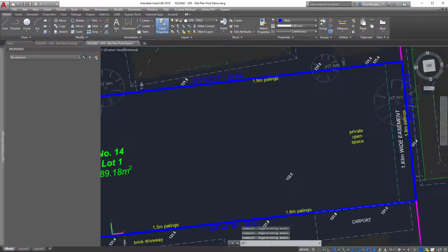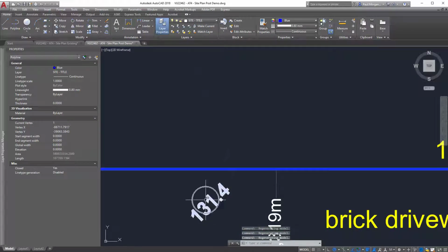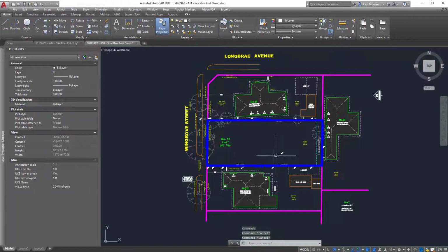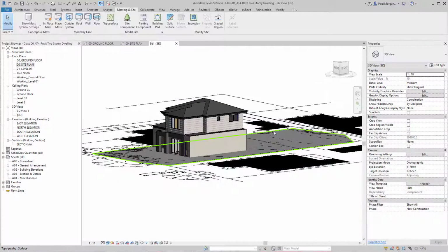Even though, if I go back to my top view, you can see that there is a height datum given for each of these contour lines. Now, that's fine because graphically it looks really clean. The model's all cleaned up. But usually when you get surveyor models, it's not uncommon that the surveyor CAD file is actually three-dimensional, and if you were to go into a side view, you would notice that those lines are not all sitting at the 0 point in the Z direction. They're all actually at different levels. So that's fine. We just have to change this around manually within Revit.